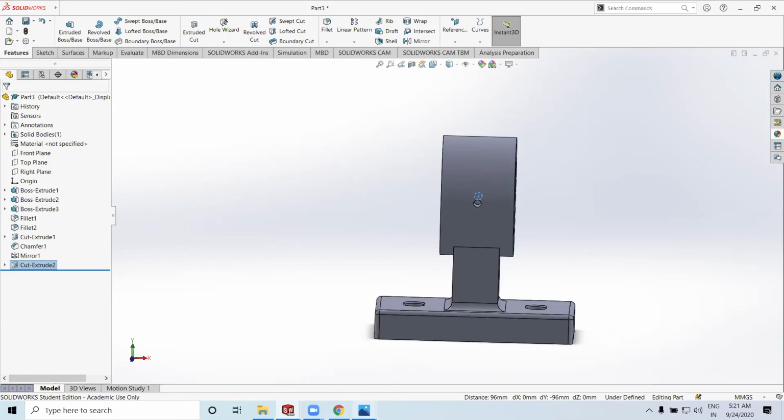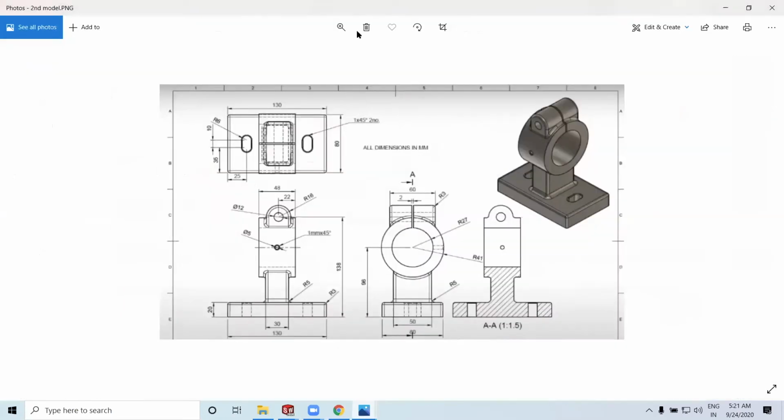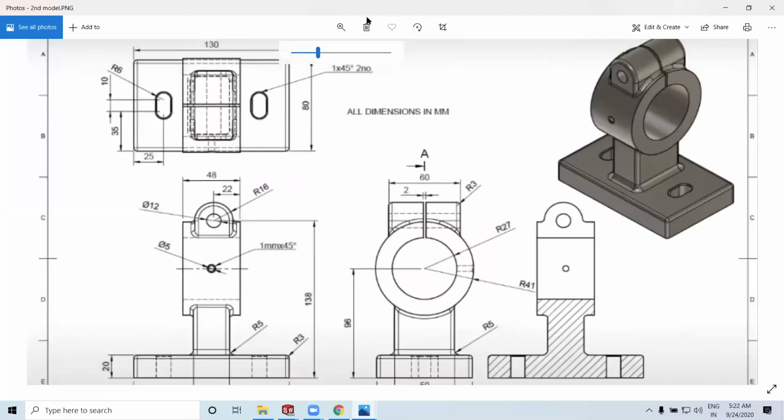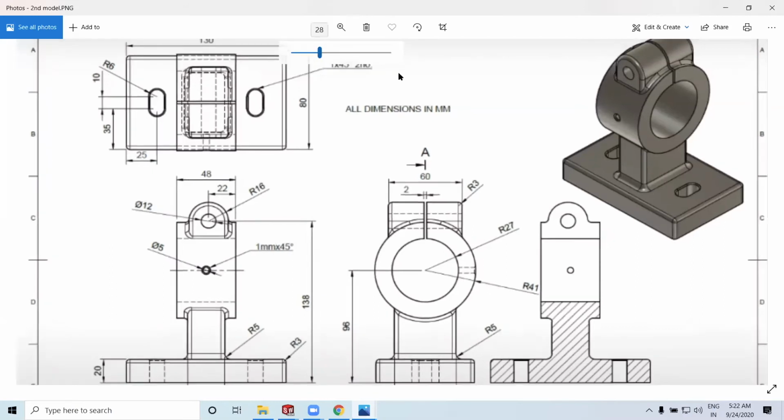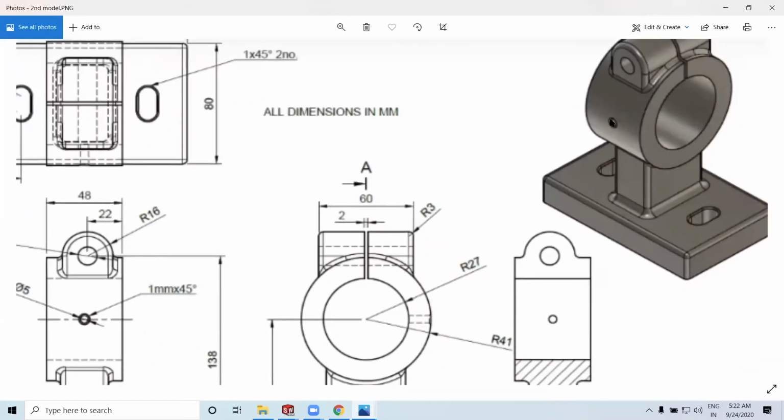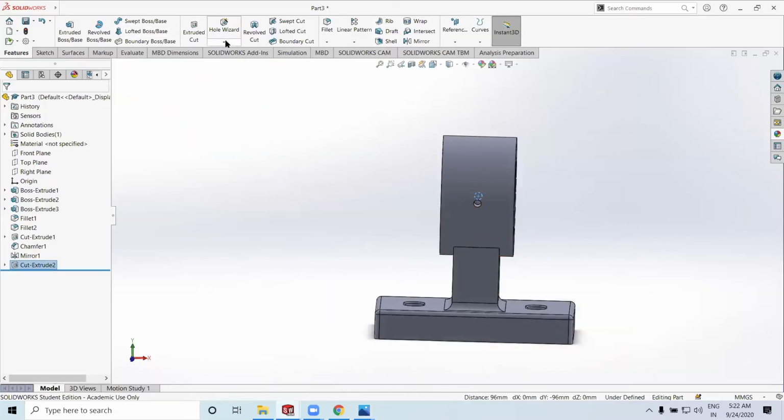That's awesome. Now the similar angular cut which we implemented earlier, we need to implement over here in the circular cut as well. As you can see, there's this second line over the circle. If I zoom in more on the model itself, you can see there's this inner angular cut which has been made. So I do that. I use the chamfer feature again. Go to the features tab, select fillet, select chamfer.